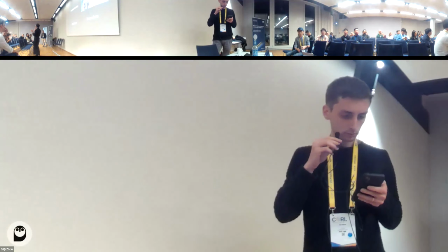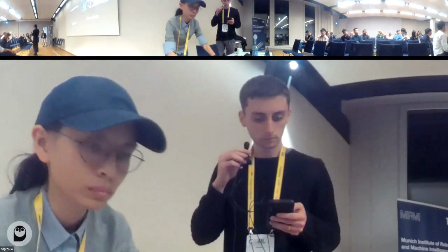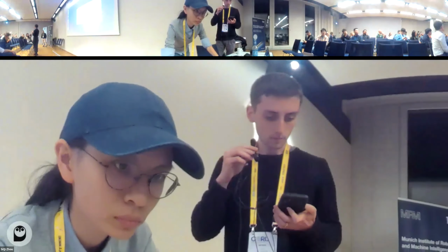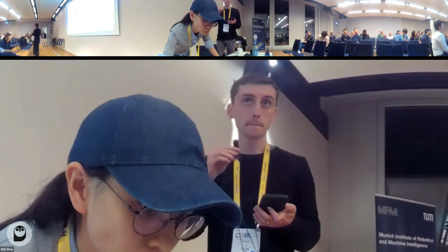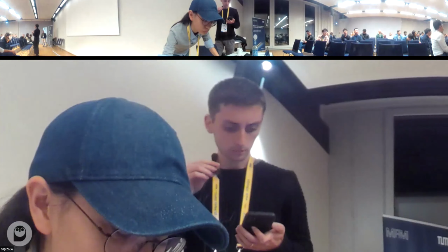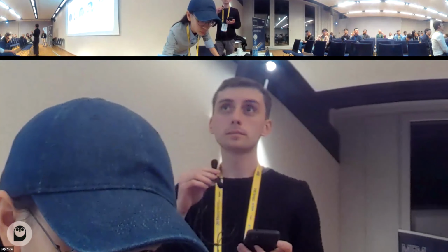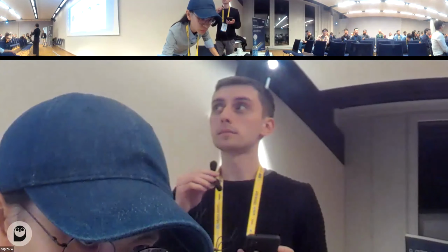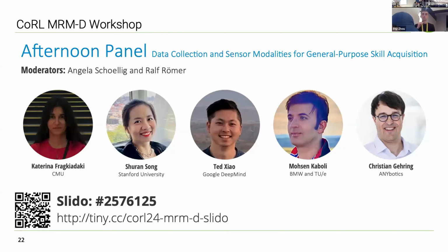And then for your second question, I kind of forgot. Yes, about whether the force is the action. In our current system, although it's a quasi-static task, it's not just taking force as an input and using it as feedback. The output is very important as well. The virtual target tells the robot what expected force it needs to execute in order to do the task. For wiping tasks, you need a certain force. In the paper, we also test different types of tasks like rotating and pivoting an object that require different forces, and the force needs to change when you're moving the object around. So it's already part of the output and part of your action space for the force.